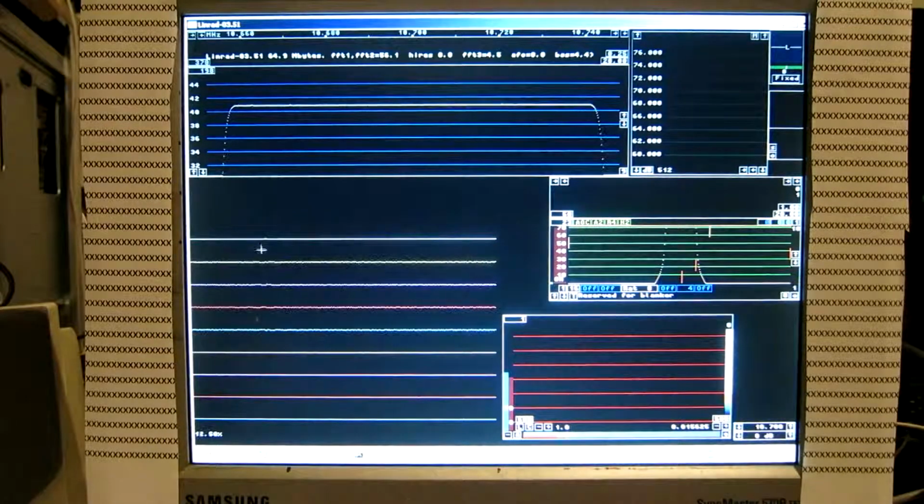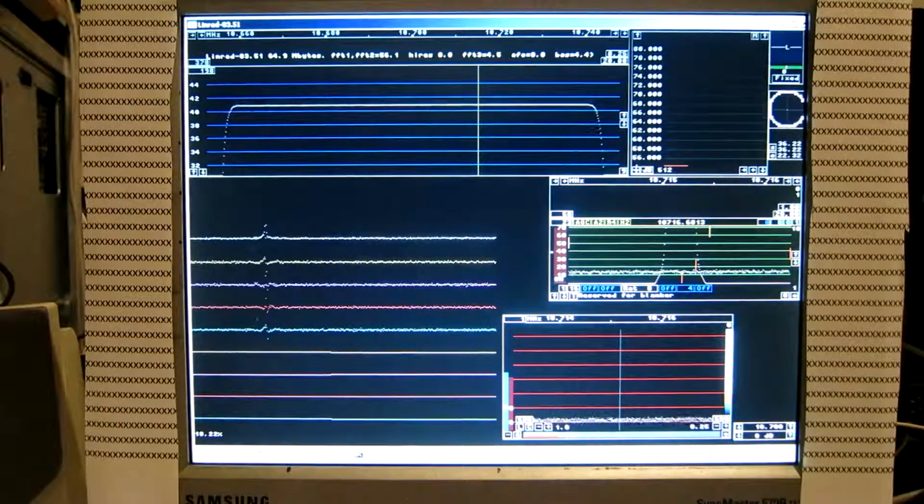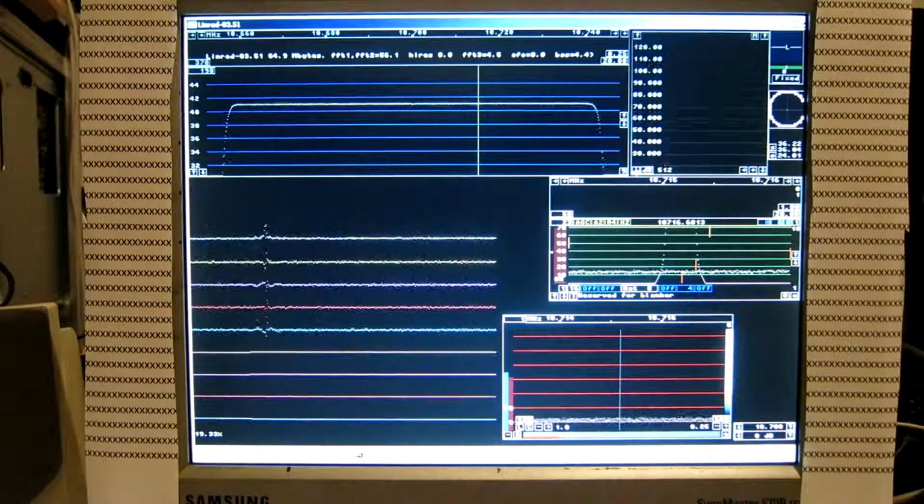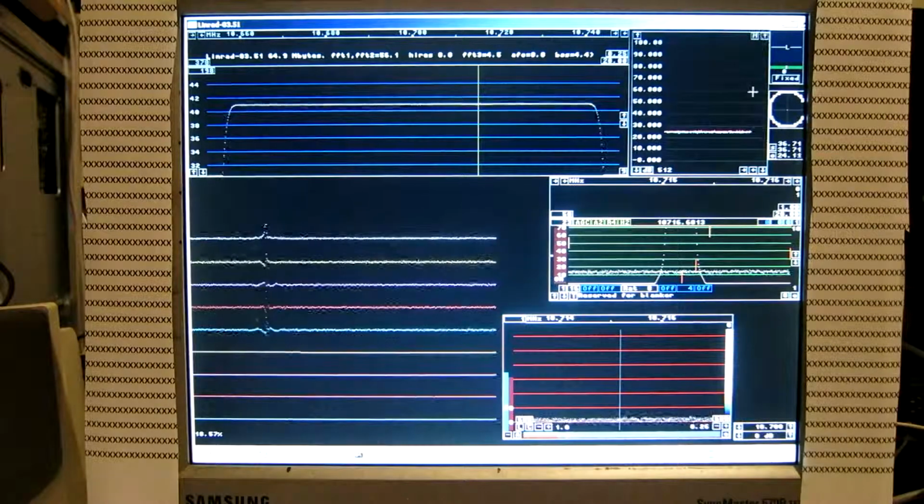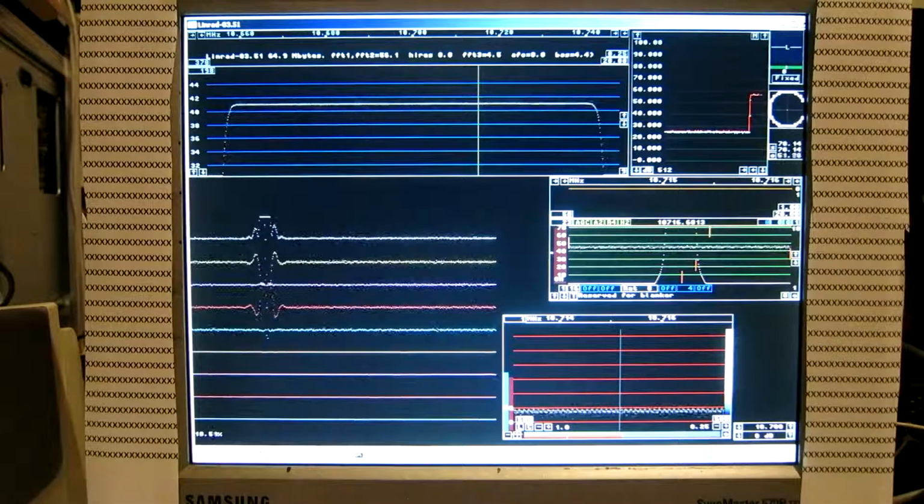And we have the blanker running, but there is no pulse anymore. We were, was it 12 dB below, I think? Plus 24, 30, 36, approximately 36 dB. Click on a frequency and make it 10 dB per division. And then switch off the blanker. So it goes from 24 to 56 dB, something like that.